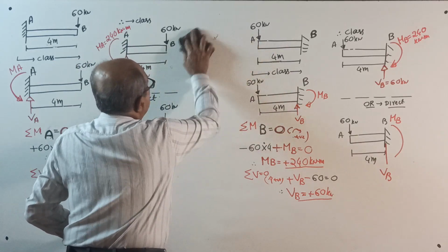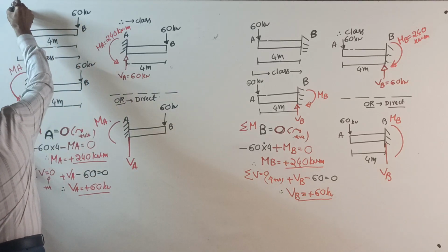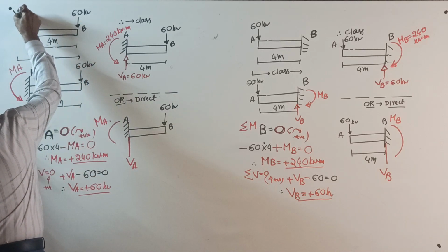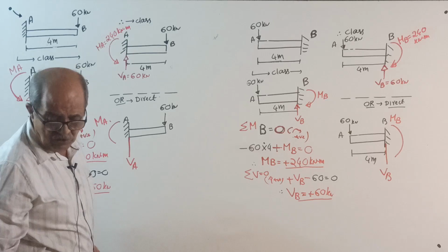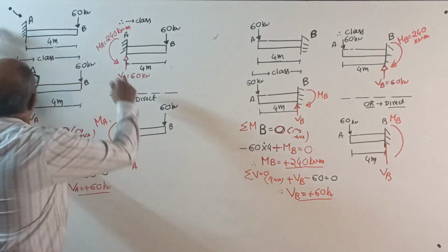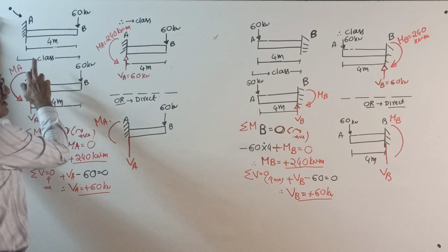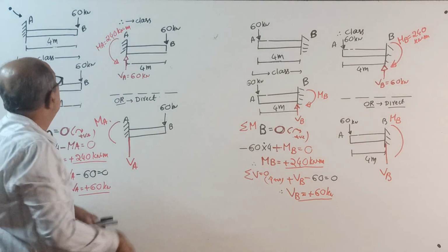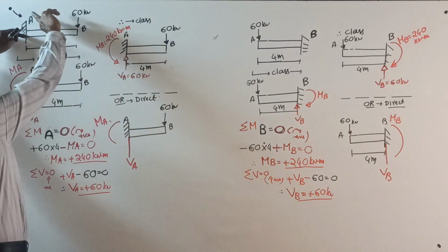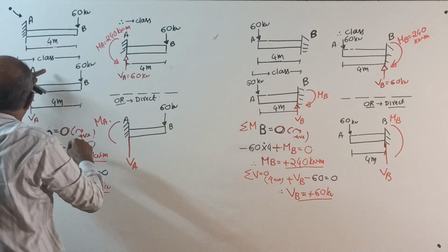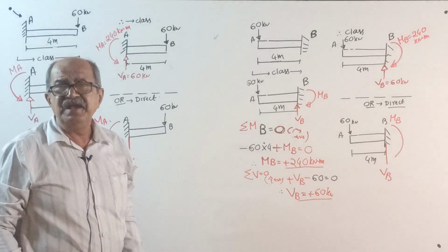Okay, start. Solution: I will start from here. This is the solution considering the left side as fixed. Now start, very fast. 60 kN, this is the given beam. Support reactions: the load acts vertically down, so the reaction is upward. This will create a clockwise moment about the fixed end, so the reacting moment is anticlockwise. I will not write this, you have to write here.